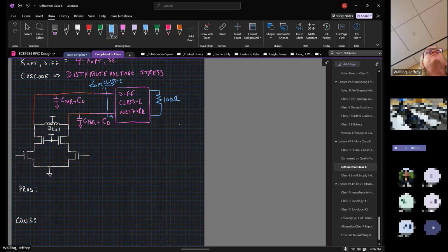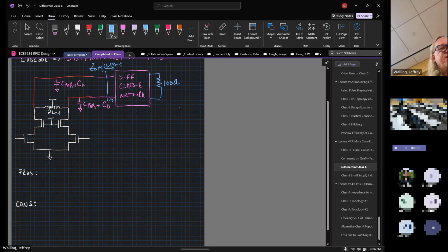This differential impedance might be 100 ohms, it might be 50 ohms, depends upon how we're designing our interface to the circuit, but I'll say it's 100 ohms for the time being. And one other nice thing about switching amplifiers, and this goes even if we were doing the single-ended version of this, these two cascoded devices pretty much just sit in triode. They don't really transition back and forth between off and triode like the other ones do. They just kind of sit in deep triode. And that means that they don't need to be fast.